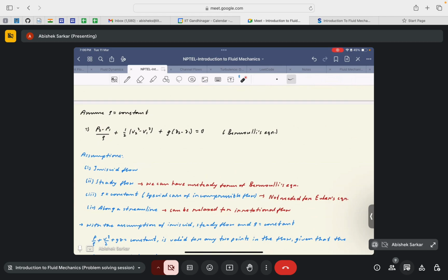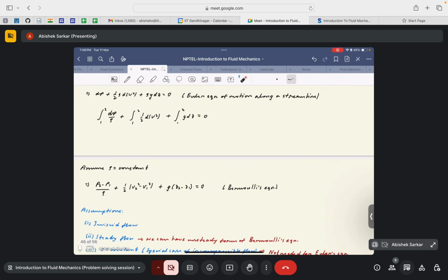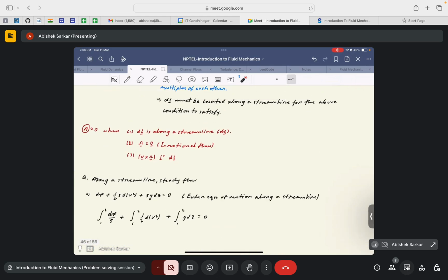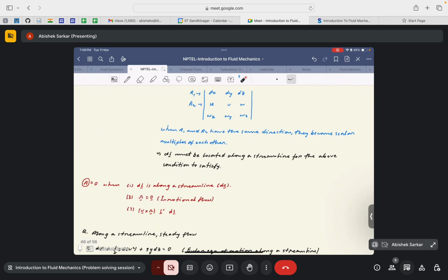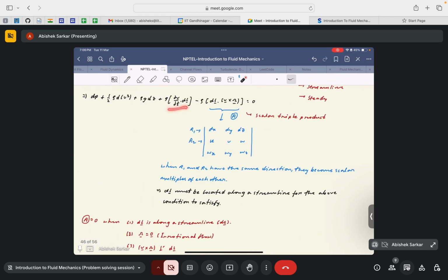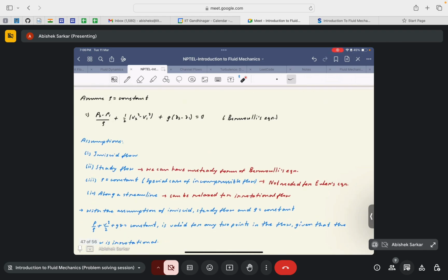First, the flow is inviscid because we are starting with the Euler's equation of motion. Second, the flow has to be steady. Again, there is an unsteady form of the Bernoulli's equation as well, where we can simplify these equations, but we have to leave this unsteady term intact. I guess we will deal with such problems in the coming week, but right now we can just say that it exists.